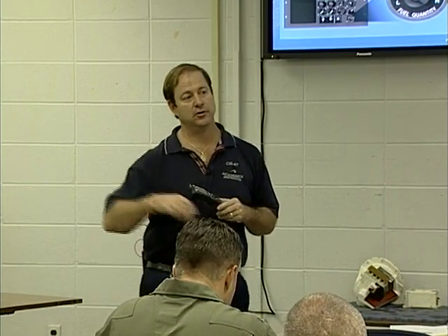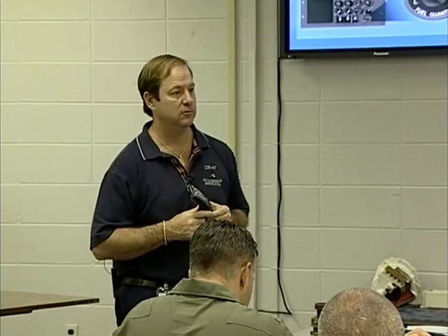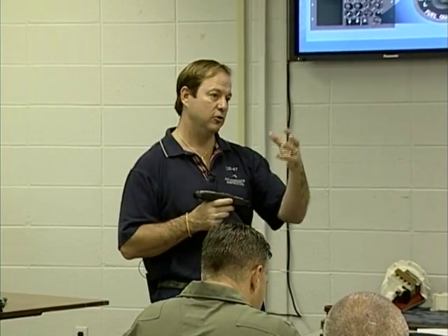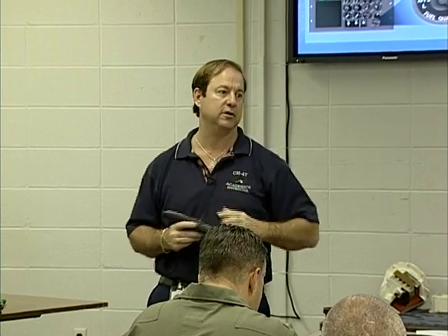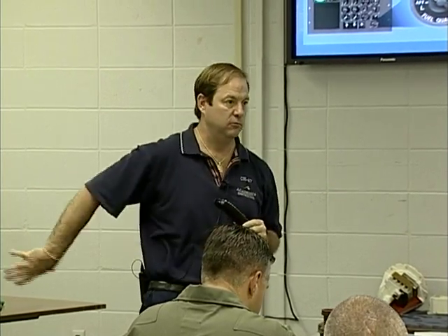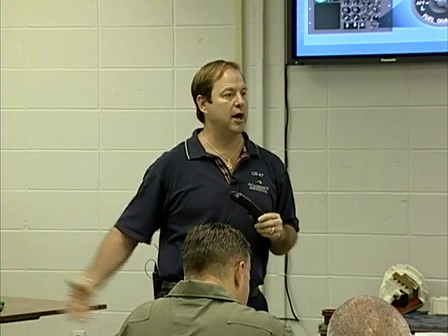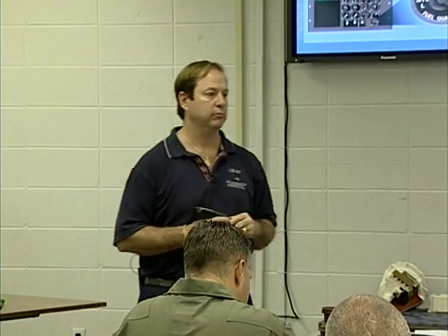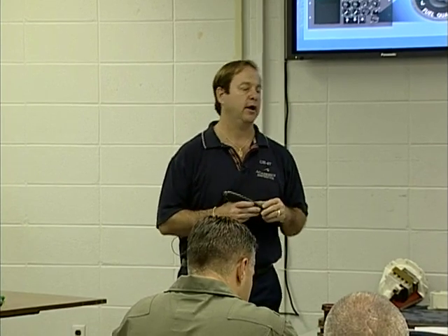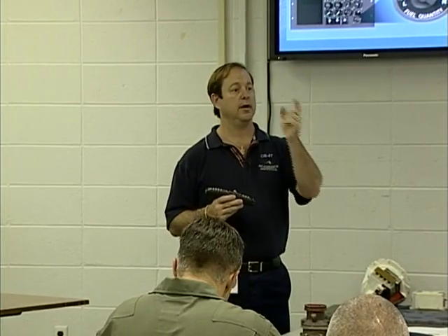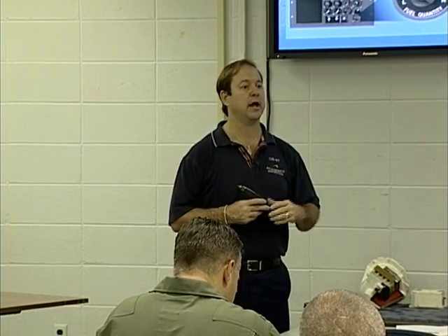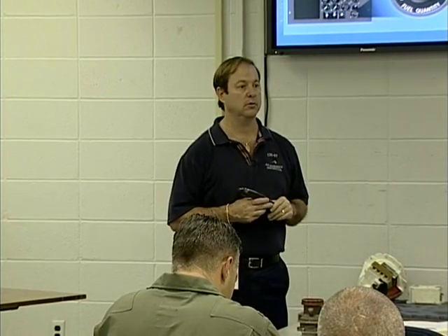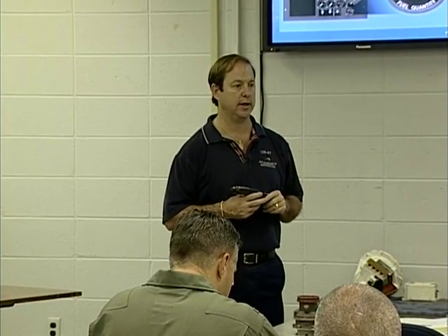And actually, when you turn on the overhead fuel refueling station, all you're doing is taking that power from the inside indicating system and transferring it to the outer indicating system, as well as powering up that panel to allow us to refuel the aircraft. And all it allows us to do is monitor the fuel quantity, and it allows us to electrically operate the fuel shutoff valves to limit the amount of fuel that we put in a tank.